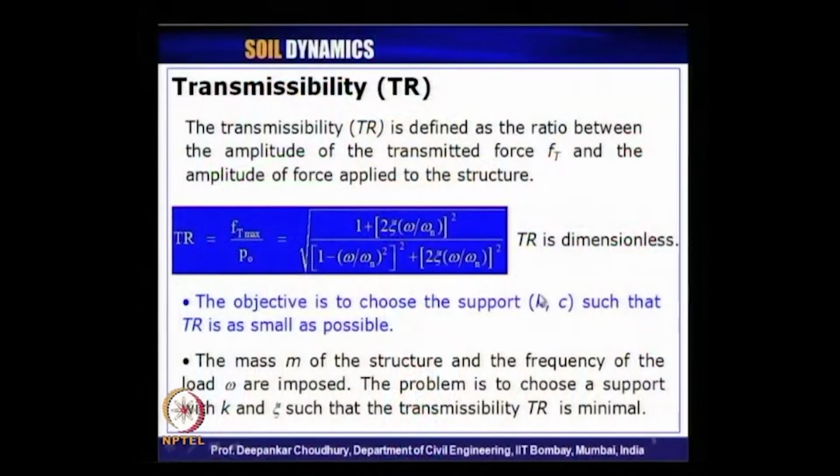So, that minimum dynamic load is transmitted finally to the foundation. So, we want this numerator f t max to be as small as possible. To have that, we can control either the support condition k or c.